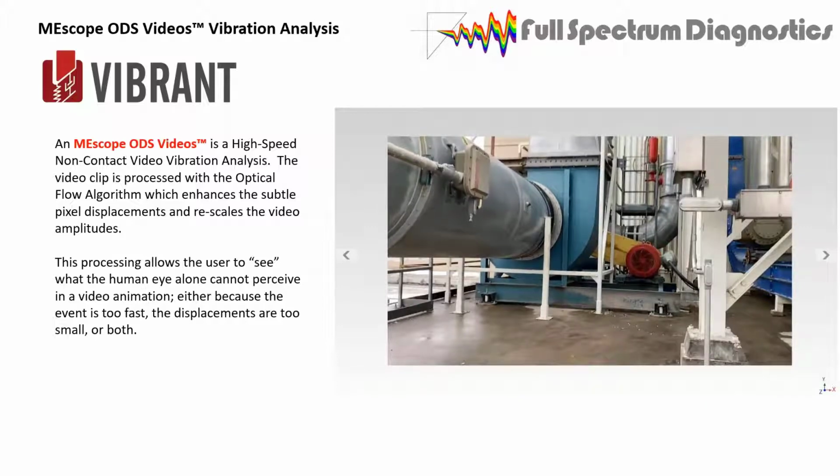In fact, it's going to be this machine you're looking at right here. This is a belt-driven fan. And it turns out that they were having a lot of failures on fans like this. This is a rooftop. It's a concrete slab that's up there. It's a big rooftop. And several of the fans kept losing bearings due to vibration levels. And we decided to do an ODS, a traditional ODS of the entire deck.